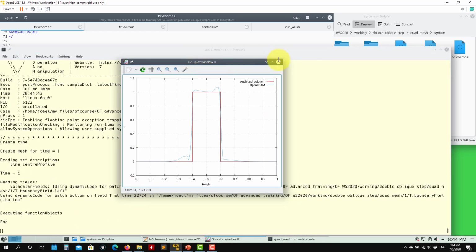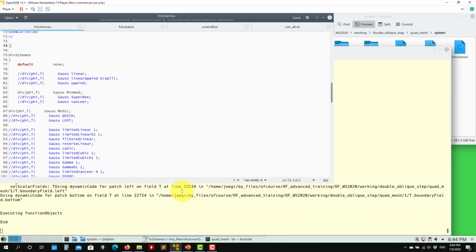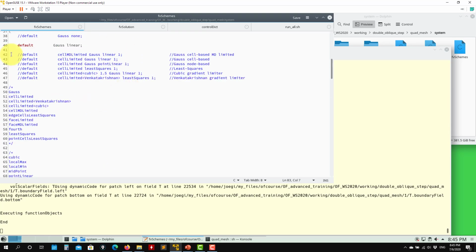Okay, so again, this is oscillatory. So let's say that we have those oscillations. Okay, let me go back to the Van Leer that was oscillatory. And probably one way to erase those oscillations from the solution can be just going there and putting the famous gradient limiter that I will add here.